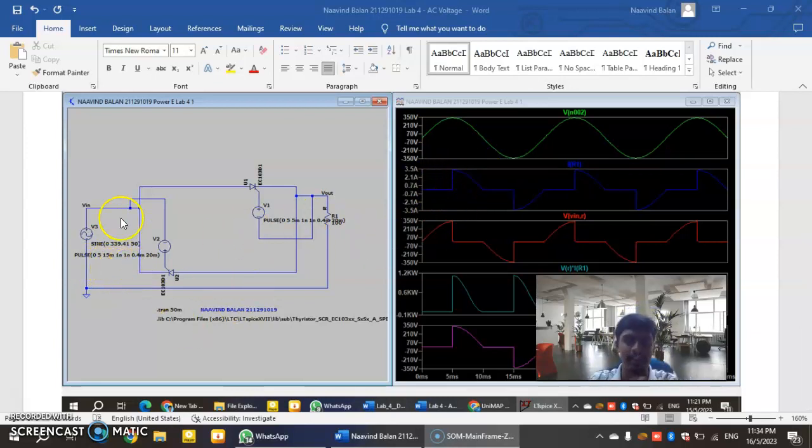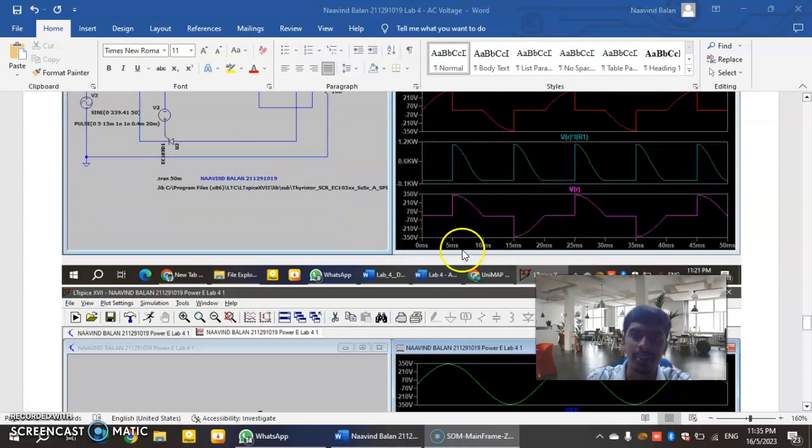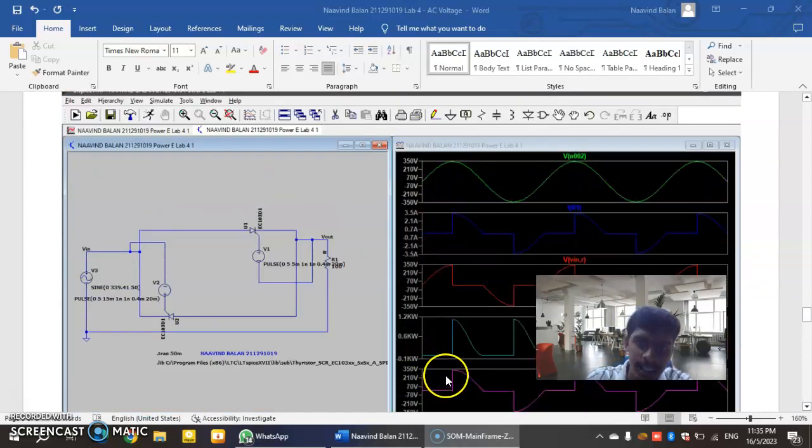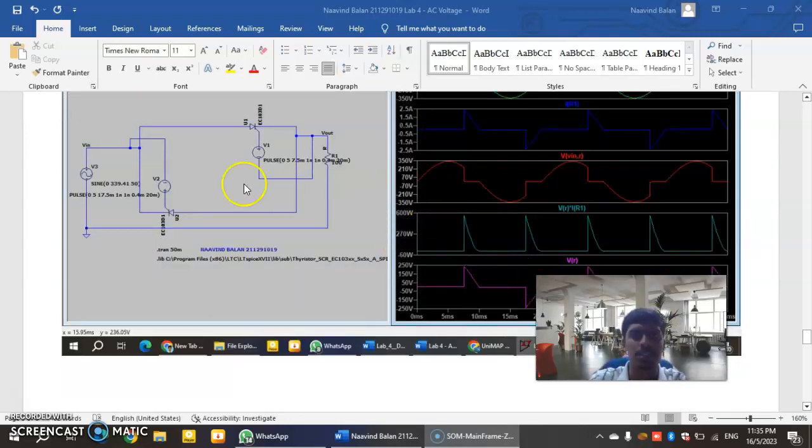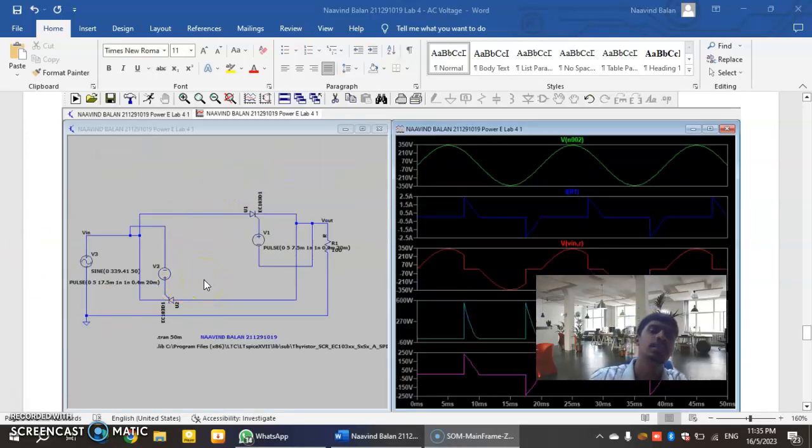So these are for the firing angle of 135. These are the input, current, input, output, the power, and then the V out. The value will trigger after the firing, once the gate is supplied. Same goes over here. This one is 175, and this will flow in the positive, and the current value only triggers when the gate opens. And then here is the same.